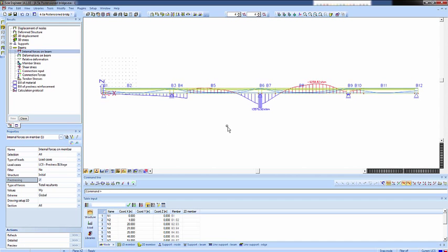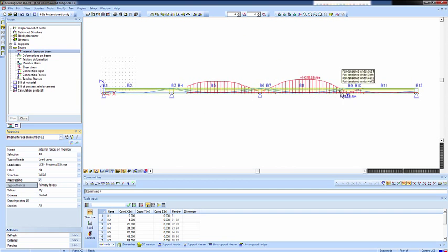But if you look at the moment due to prestressing, then you get several jumps, positive and negative moments. But the moment that has been introduced by the prestressing is not equal to just taking the normal force from the prestress and multiplying it with its eccentricity. If you would do that, you would have the primary forces. The primary forces give this moment. So actually you're picking these tendons together and they would give this moment.